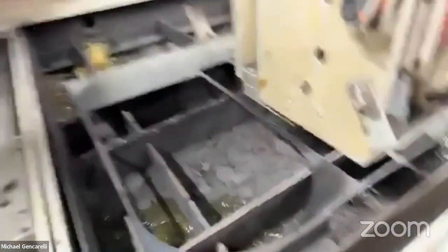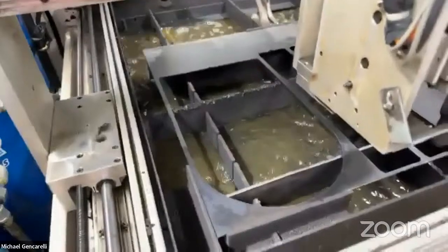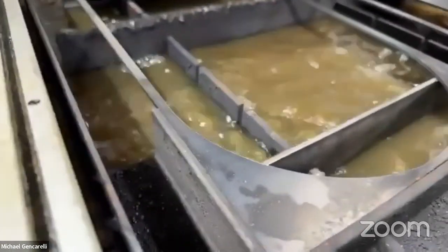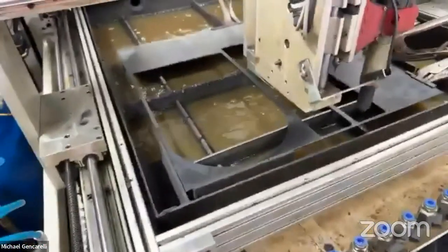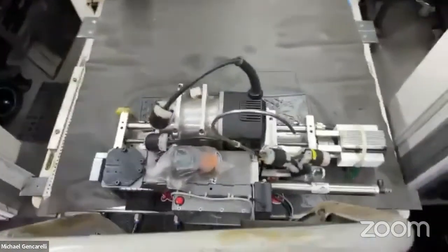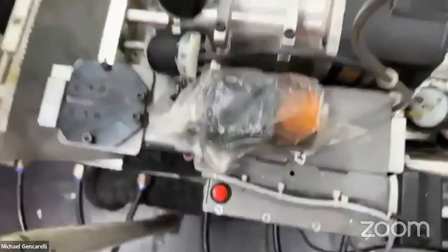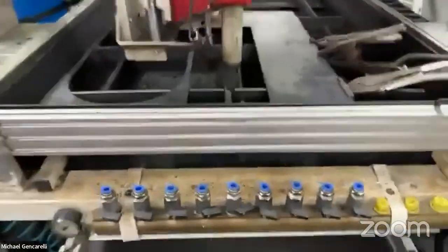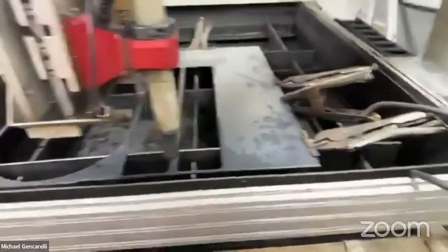Then I added a dual chamber water table. So I add air to the bottom tank and it pushes the water up to the top tank. So I can fill the plasma table with water in 15 seconds. And then when I want it to be a router again, I've got a vacuum table underneath on a hydraulic hoist because I've got a bad back. I've got my router and a laser, right? So I can engrave and route. And then the vacuum table just jacks up and slides right over the dual chamber water table. And now I've got a 3-axis router with a vacuum table.